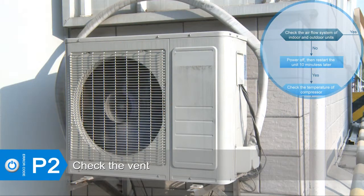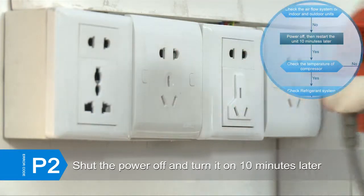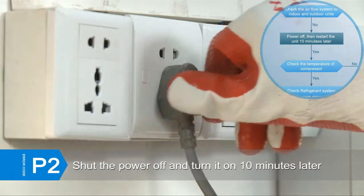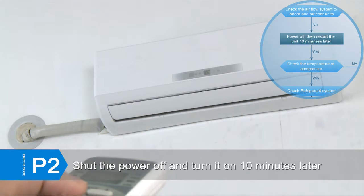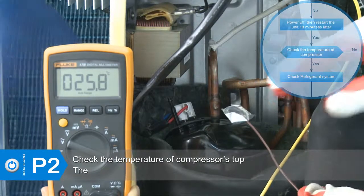Check if the ventilation of the indoor unit and the outdoor unit is obstructed. Clear up the air inlet and outlet, or the heat exchanger of the indoor and outdoor units to make sure the ventilation is good. If the error still exists, shut the power off and turn it on 10 minutes later. If the error still exists, check the temperature of the compressor's top.